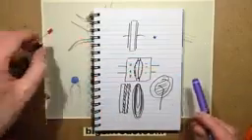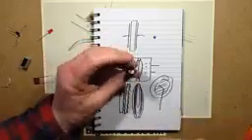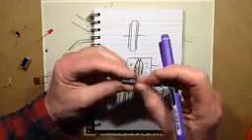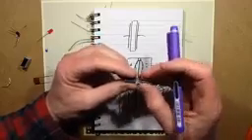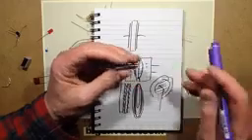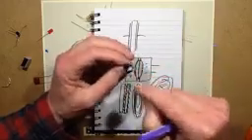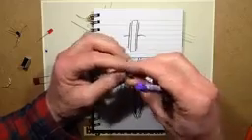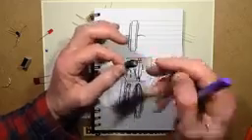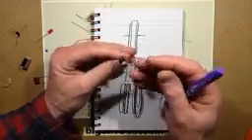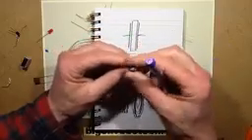So, electrolytic capacitors are one of the more exciting capacitors, and I don't mean that in a good way. To achieve such a high capacitance, they contain a liquid electrolyte. And they have a very thin foil inside. And to create an extremely thin insulator, they form an oxide layer on the aluminium foil in there.